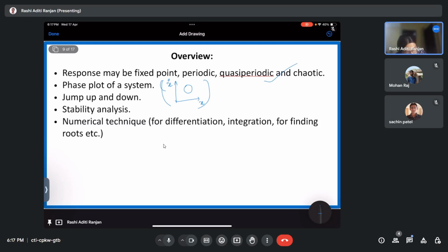frequency response. So in case of a nonlinear system, we know that we are going to have something like this, a bend in the frequency response. So what is going to happen if I keep on increasing my omega for the system? I just started with 0 omega and now I start increasing my omega. My system is going to follow this path till here. After this, it does not have some place to go. So what will it do? It will not come here. No, it will jump from here to this point, and then we'll start following this.